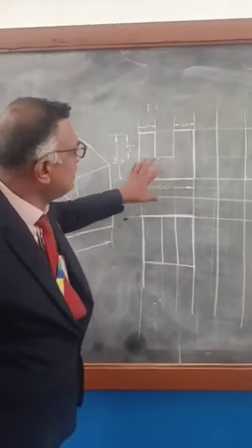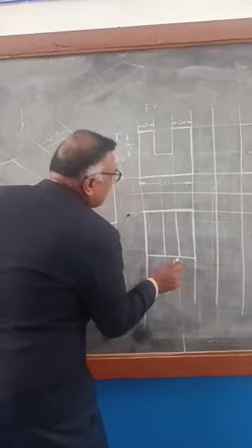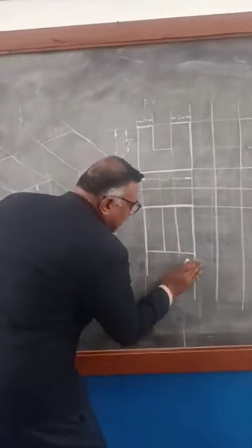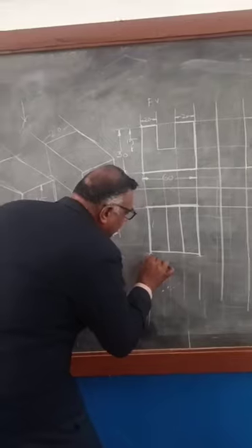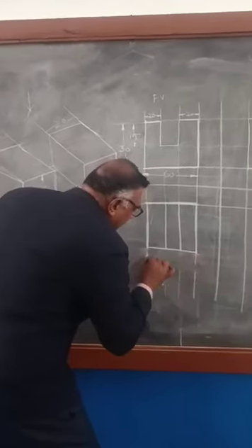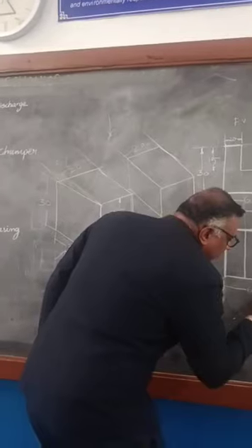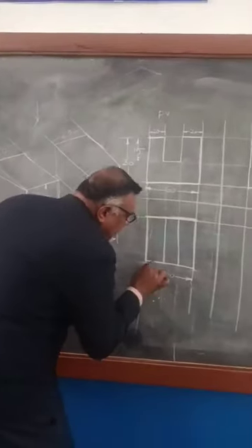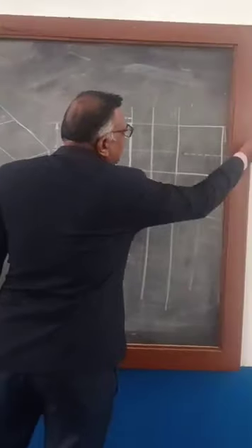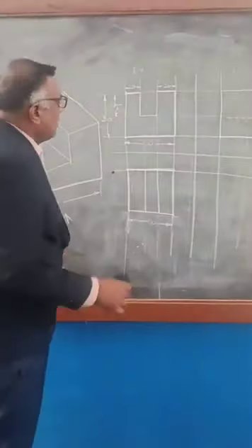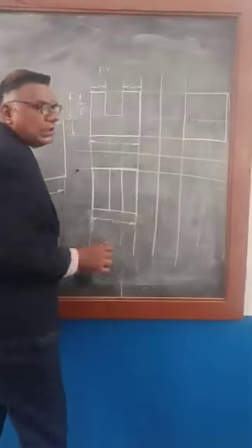It is compulsory to mark all the measurements in one view. Instead of 60, you can draw it here at 60 mm. Give a gap of 2 mm, 12 mm, 60. Put the arrowheads like that. If the 30 is not visible, you can draw it as 30 mm on this side. So this will be the front view, top view, and the side view of the component.